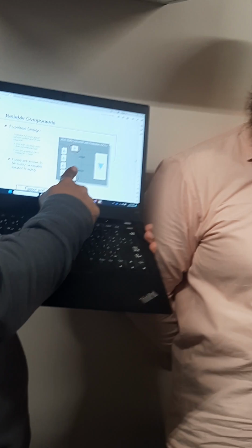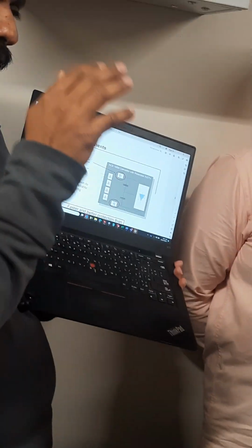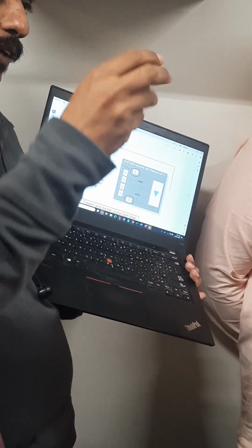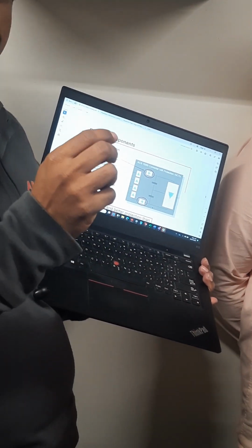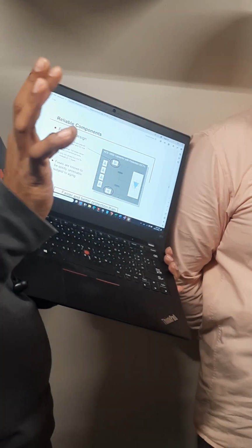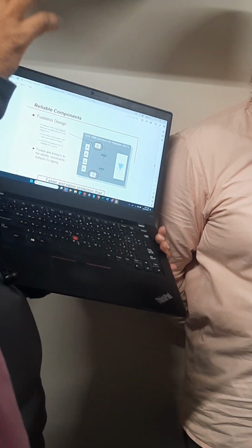One goes inside the drive, where it converts 11 kV to 3.3 kV, and the other goes to the auxiliary transformer, which converts 11 kV to 450 volts. From the same transformer we take the three-phase auxiliary supply for the drive, which we use for the fan and the control circuit. In the other, smaller drives, we get the three-phase supply from external. For 5 and 6 you are giving three-phase external supply because there is no 415 volt transformer. You need to keep that in mind.